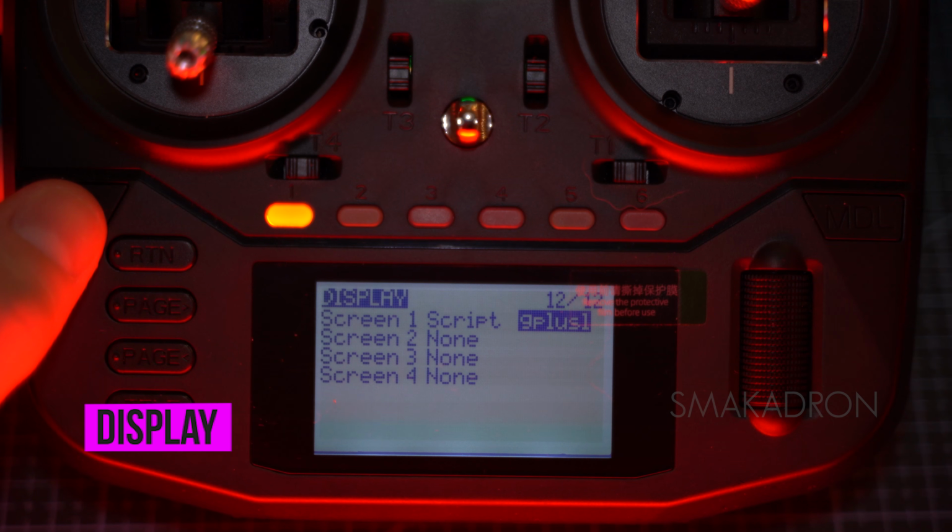Script. This type executes a configured telemetry Lua script. The telemetry Lua script must be located in the folder on the SD card, scripts, telemetry, to be available for configuration. These parameters allow you to customize the display of telemetry information according to your needs.